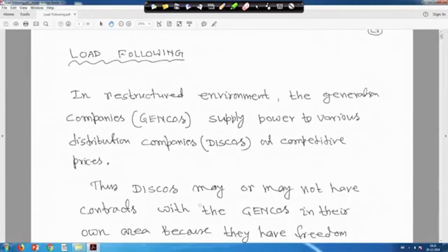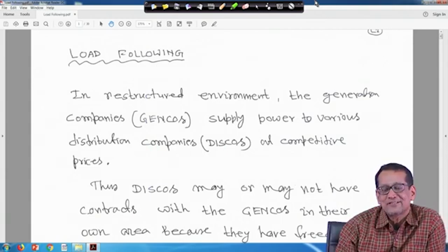Okay, we are back again. Although the previous one was also load following, this is another version, another type of modeling. I told you what load following is. When a load disturbance is there, generation will chase the load such that generation matches the load. In a steady state ideal condition, generation is equal to load plus, of course, losses, but we do not consider that.